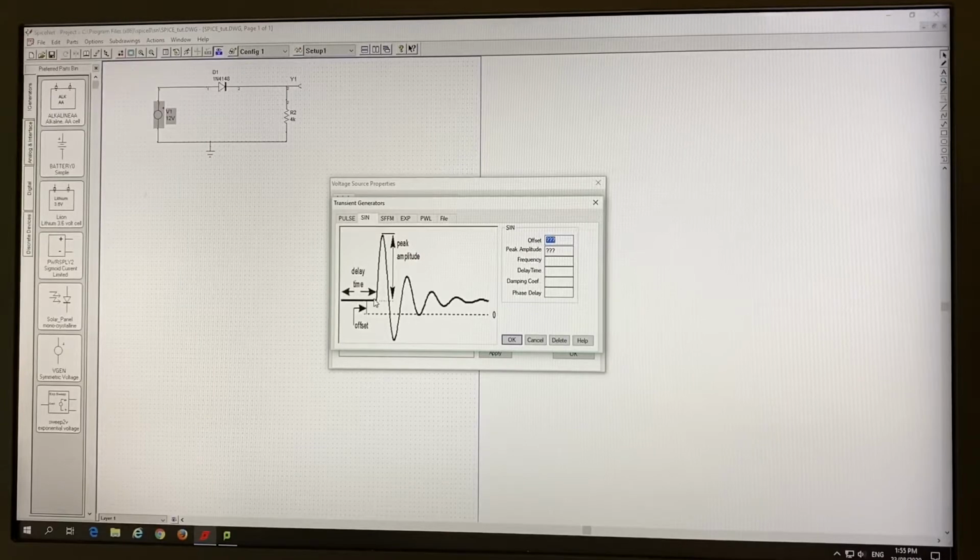If I offset it by maybe 2 volts, my peak will rise from 10 initially to 12. But then my negative voltage won't go to minus 10 anymore. It will just come to minus 8, because peak to peak has to stay 20. You're just offsetting it.